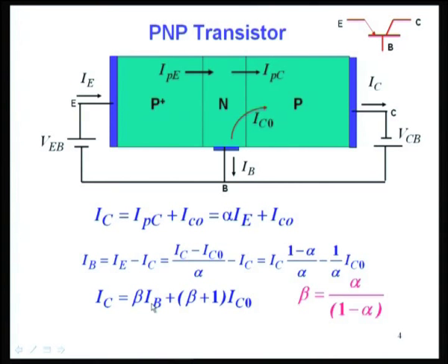collector current divided by the base current. So, here I take the collector current divided by the base current, that is the current gain in the common emitter configuration. If I use this as input, make that the common terminal. So, beta is collector current by base current, neglecting, of course, this, which will be very small, it is the reverse saturation current part of it.